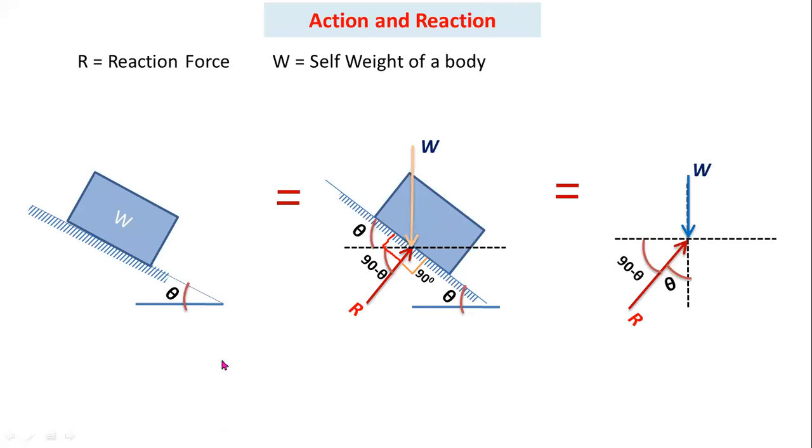Please note down this diagram. It is very important for the engineering mechanics subject. So this is the given diagram. I converted this given diagram into a forces diagram. Here the self weight of the object you have to consider vertically downwards. Always you have to consider self weight as a vertically downward force.